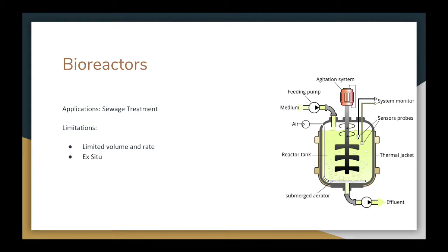A bioreactor consists of an engineered vessel that creates an environment that promotes biological growth, allowing the reproduction of microorganisms in hopes of taking advantage of a chemical process that will take place as a result of these organisms feeding. This remediation method is considered to be both aerobic and anaerobic, meaning that it can be applied to several different substances requiring a large range of chemical processes in order to degrade the contaminant.